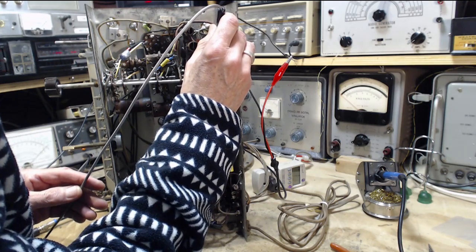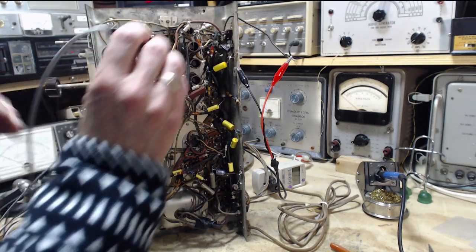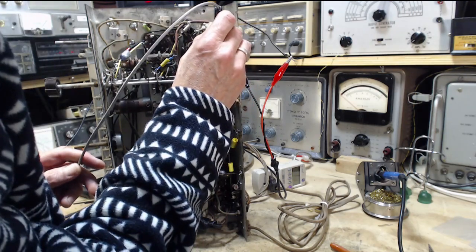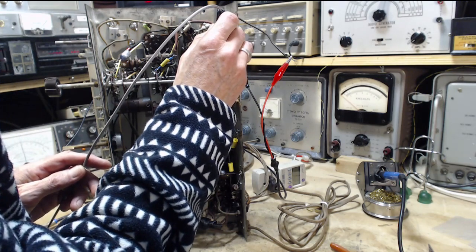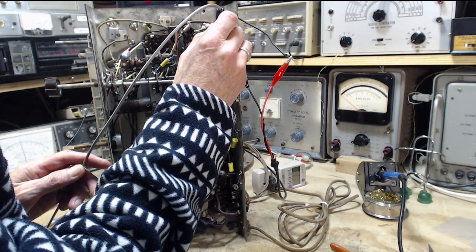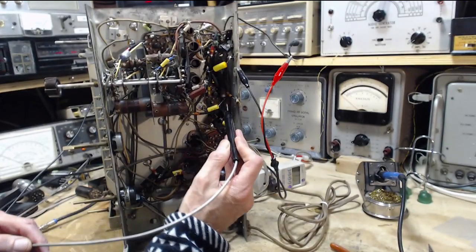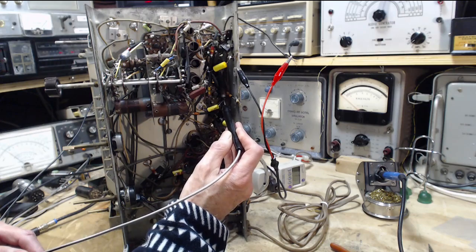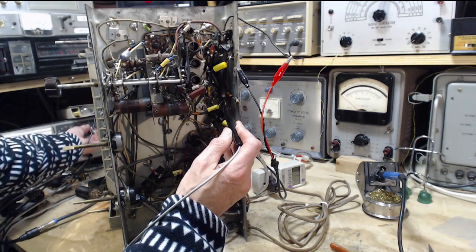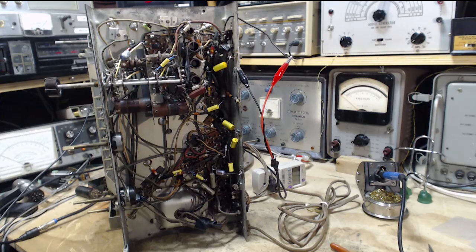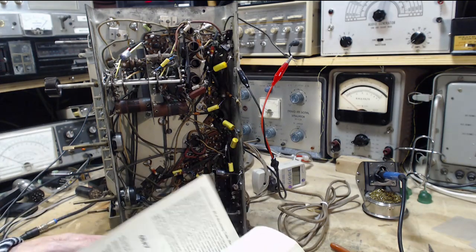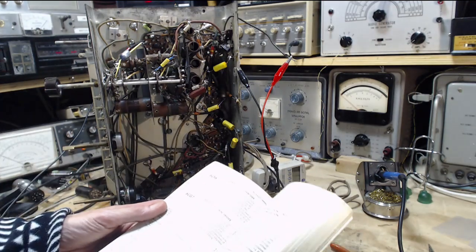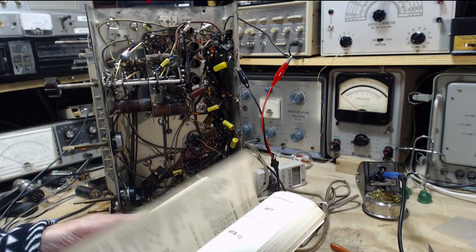The other side, okay, I can see the meter going right over in the corner of my eye here. So this must be the B plus side here. Okay, so I'm kind of blocking the meter. That's reading almost 250, and on the other side we're getting 75. That sounds a little low. Let's check the book. What does the book say about this? So we can pick any one of these tubes. We'll pick the 6K7 again. 6K7.